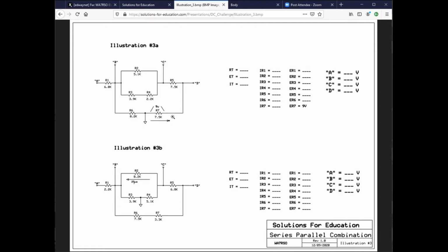Aha, now you're catching on. So here we know the resistance and the current going through this resistor, because 9 volts and 7.5K, just a little over 1 mil, right? And then lo and behold, that current is the same over here through this resistor. So now we can get an IR drop here. And pretty soon then this collective IR drop and IR drop here is what is across this. So how much current is going to flow? Oh, well, to figure this out, you have to figure out these 2 resistors in series, put them in parallel with that, then in series with that to make a collective resistor. And when you have that one resistor, then you can figure out that the voltage between here and here is the same as between here and here. And now I can figure out how much current is flowing in that circuit. So you see, the whole thing is a deductive reasoning. This is a legitimate test. This whole thing right here, legitimate test. I've used this in the classroom for years.